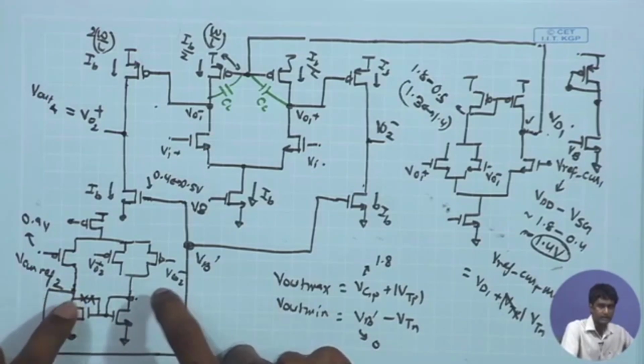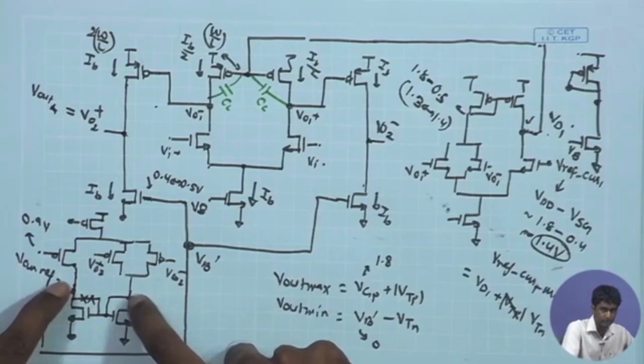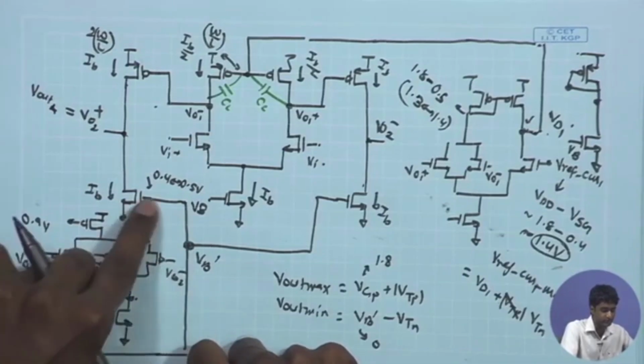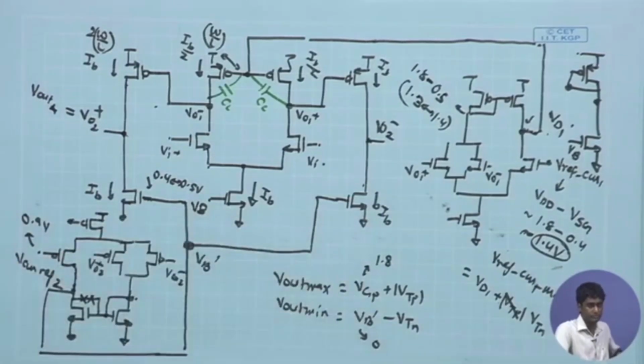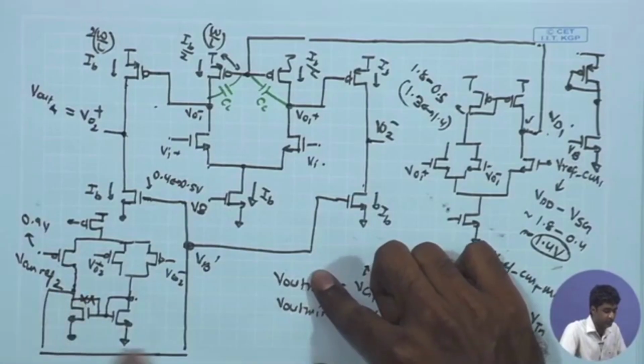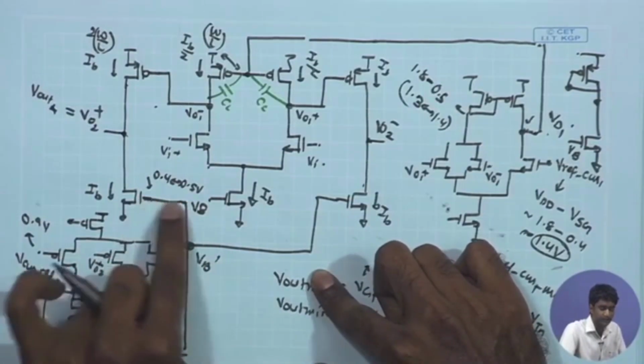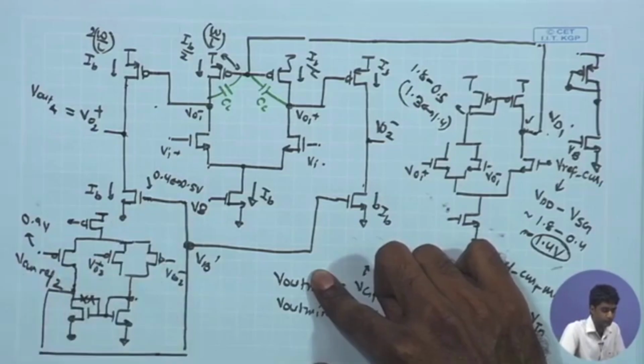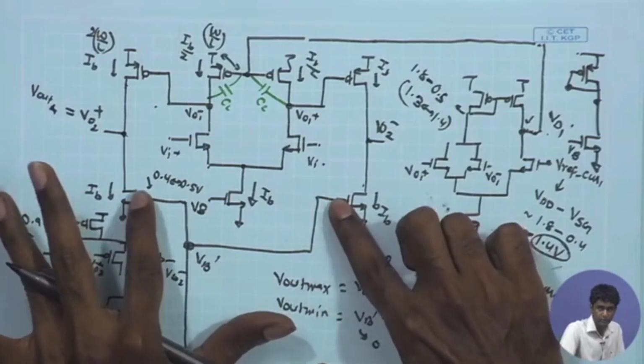Therefore, the drain potential of these two NMOS is going to be close to VGS of NMOS, which is fed to these two NMOS also. So, the output DC point is naturally close to the gate potential of an NMOS. Therefore, I would like to use the error amplifier with PMOS as input device, NMOS as load to bias the current sources over here.